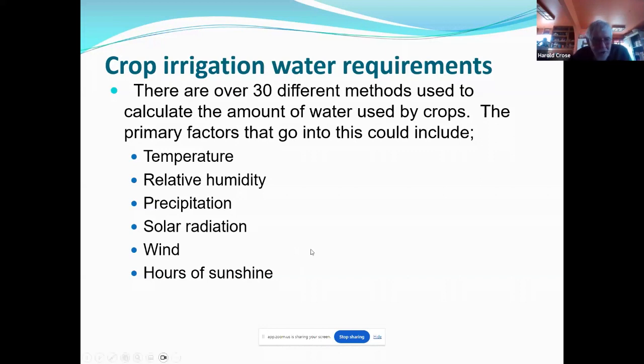And there's charts and maps that show you different crops and how they do with different levels of sunshine. And the crop coefficient, we'll get into that a little bit more. Each crop has a coefficient assigned to it for how much moisture it actually takes. Before we had soil monitoring devices for soil moisture, we used an evaporation pan. You could measure the amount of evaporation over a 24-hour period, apply the crop coefficient to that, and it would tell you how much water you had to apply for that crop. So crop coefficient is important.